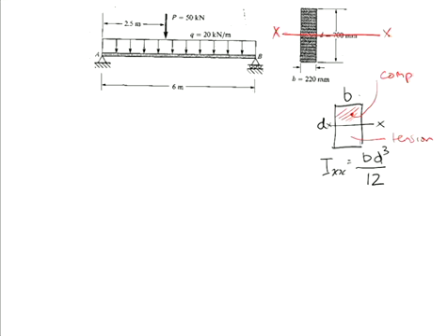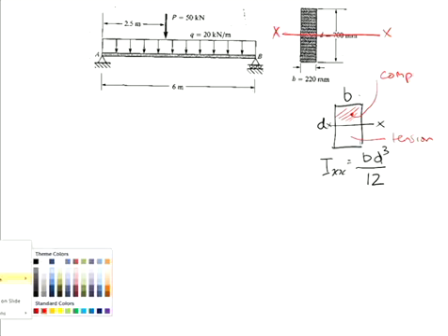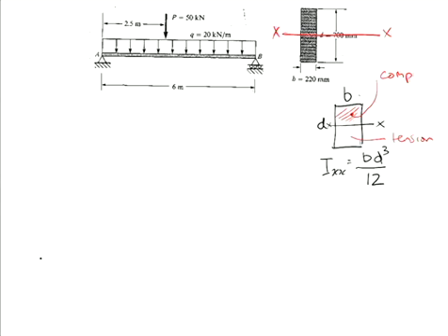Okay? Okay, so doing this problem here, the first thing we need to do is draw our bending moment diagram. In order to do this, we need to calculate our reactions. So let's take moments at A. Again, we're going back to basics. Our moment is 50 kilonewtons times 2.5 metres. It's anti-clockwise. No, it's clockwise, so it's negative.